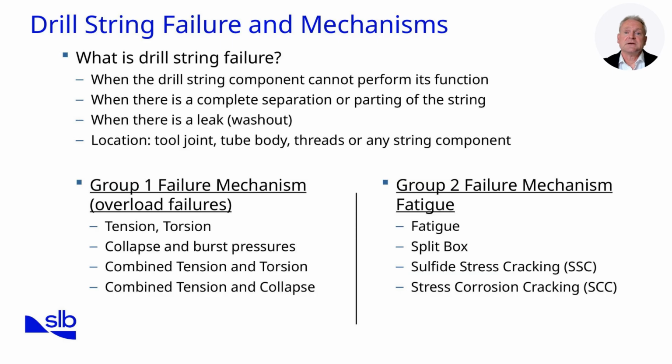Drill string failures occur when the applied stresses exceed the material or design limits, and they represent one of the most costly problems in drilling operations. Failures can be grouped into sudden overload events or gradual fatigue-related issues. Overload occurs when a pipe is subjected to stresses exceeding its yield or tensile strength, resulting in catastrophic breaks in